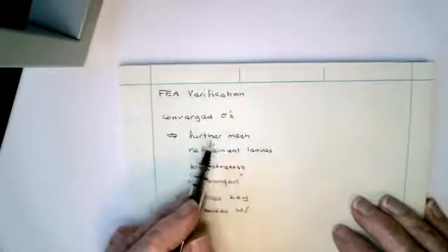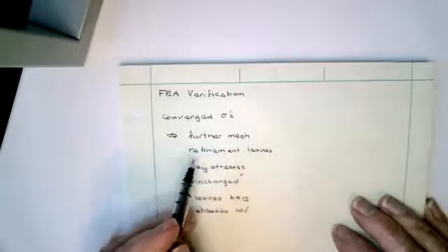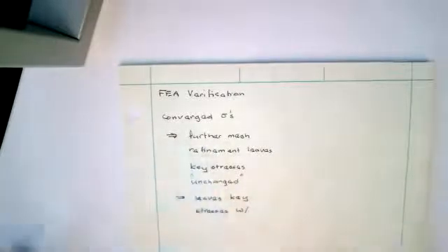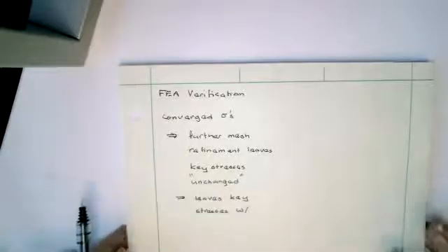Okay, we're going to talk about how to refine your mesh, and that will reduce your error. And so you've converged if you keep on refining, and then nothing's happening to your key stresses. There's no further refinement.